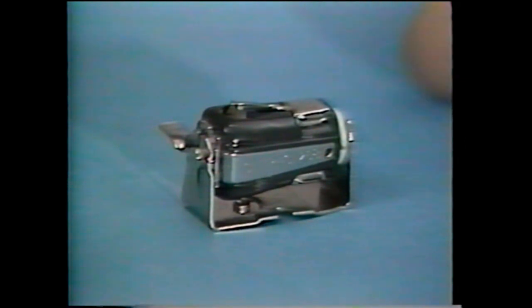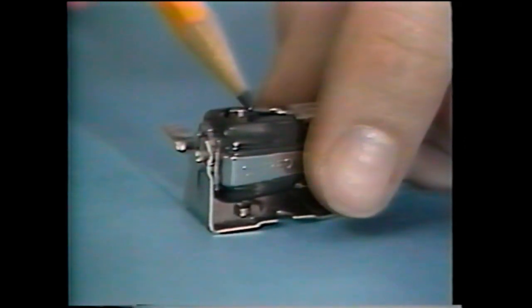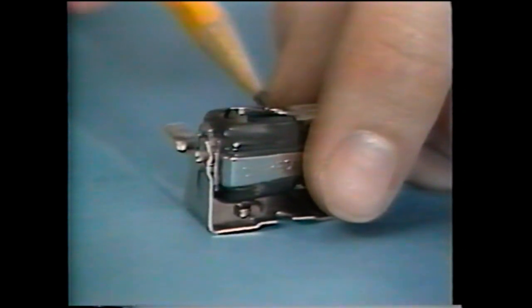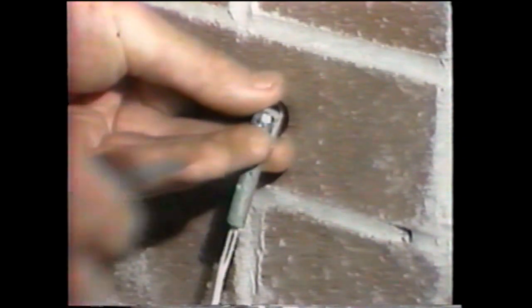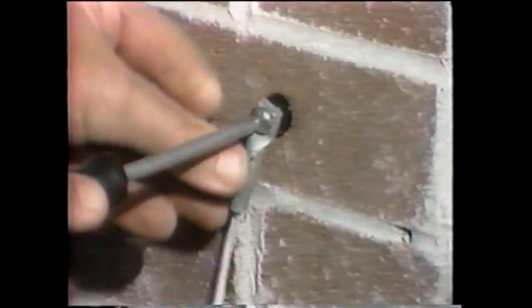There are several commonly used methods for generating voltage. One method is friction. By rubbing certain materials together, the electrons move from one material to the other, thus producing a voltage. A second method is pressure. By squeezing the crystals of certain substances together, voltage is produced. A third way is heat. By heating the junction where two unlike metals are joined together, voltage is generated. A thermocouple, used for measuring temperatures, is an example of this.